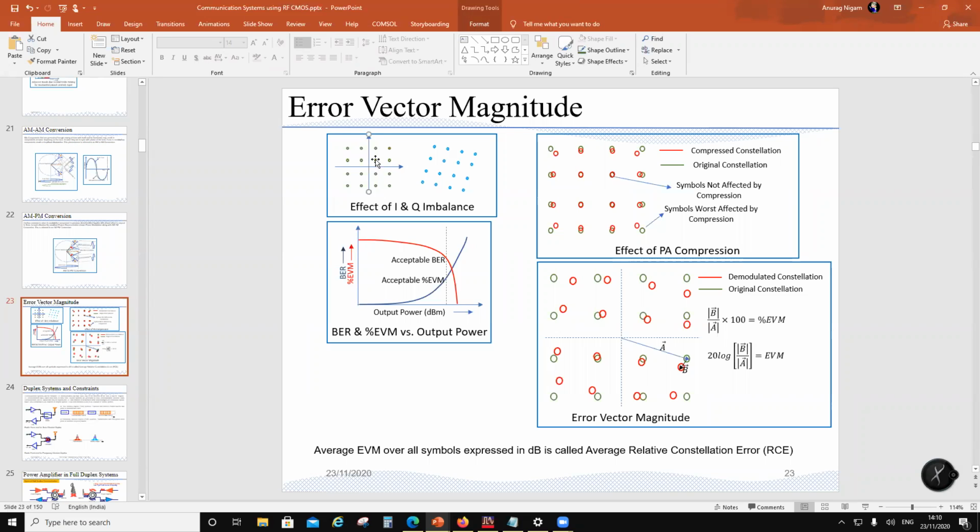Now, if I'm jumping from one bin to another, I and Q are changing. That's what a QAM is. Basically we work with symbols, and with certain rectangular coordinates, which I call I and Q. If I want to send I and Q signals, I can modulate the same frequency: one I modulate with a sinusoidal waveform, the other with a cosine, because sine and cosine are orthogonal.